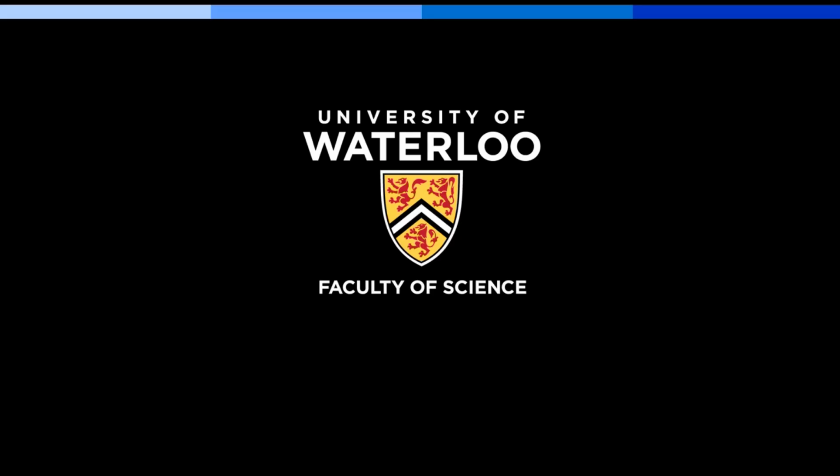So my recollection, R squared was the main one we were looking at. We knew that, based off the data and the hydraulic head measurements we had available to calibrate it, having something really rigorous for calibration was not necessarily reasonable. There was so much uncertainty involved. As I had said, Adam had gone out and visited this site with Bluemetric, chatted with the folks who've been working there for a really long time, and got an understanding of how the flow system probably occurs on top of those available data. So we did use R squared.